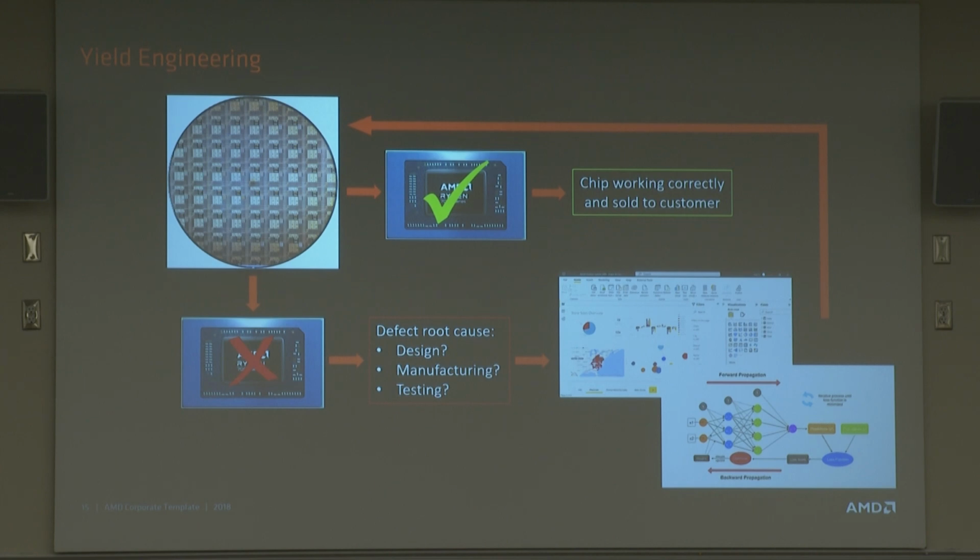Basically, that means, are we testing the part incorrectly? Are we giving it too low of a voltage? Are we giving it too high of a frequency? Basically, are we excessively stressing the part? And so what a yield engineer does